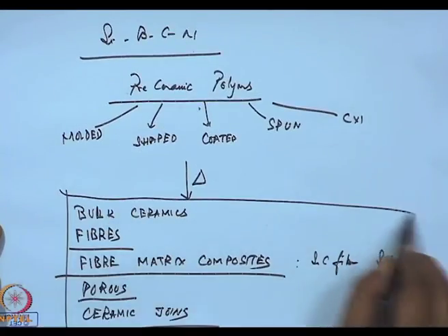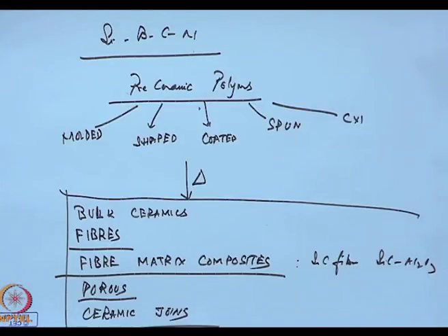So, these synthesis of silicon carbide nitrides by the polymer pre-ceramic routes help us in obtaining these huge areas of materials, especially the fibers, which allows us to have high temperature refractory ceramic carbides, nitrides or SiBCN into shapes which are easily handleable.